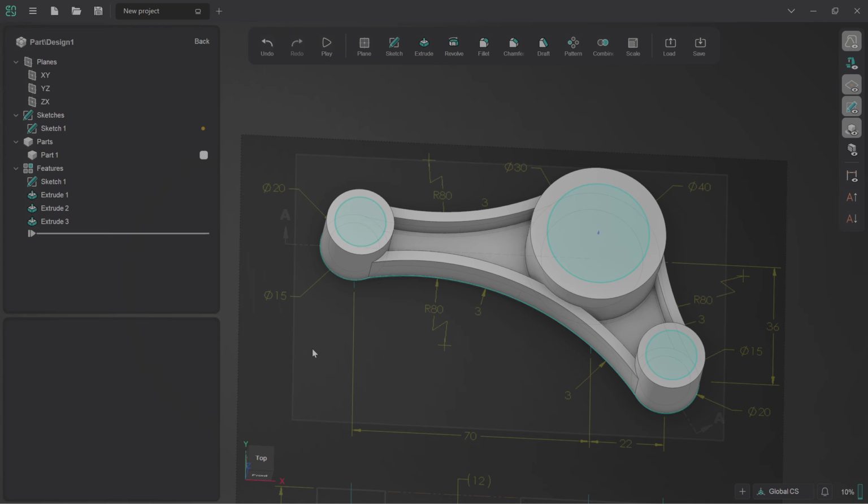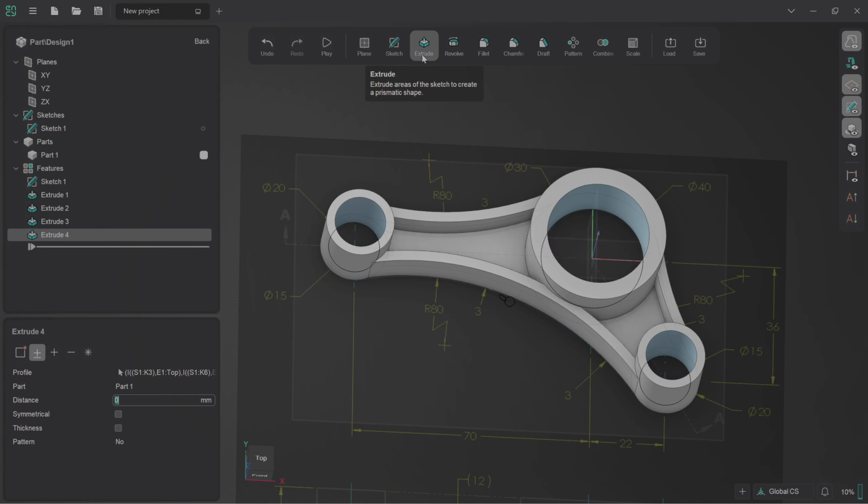Anyway, we're going to do one final extrusion process, which is going to be for these inner bores. We're going to use the extrude tool to pull instead of push in this case. So I'm going to click on extrude, and it automatically defaults to 0 because it can detect that it's inside another element and you might be wanting to use that as a borehole, which is precisely what we wanted. So we leave that as is. That's all good.